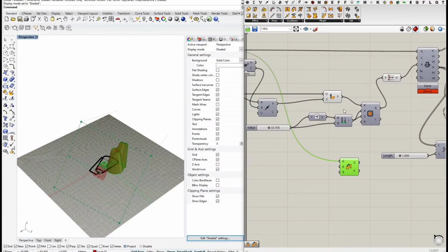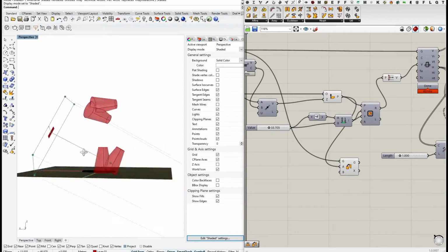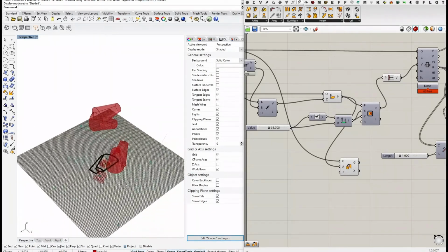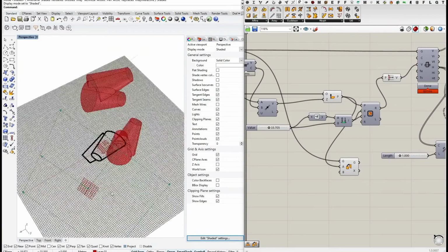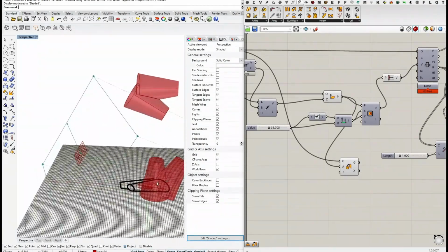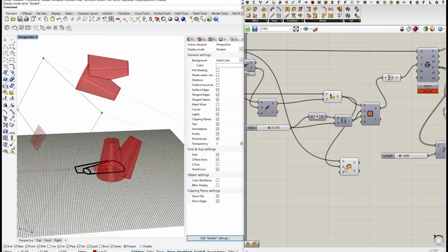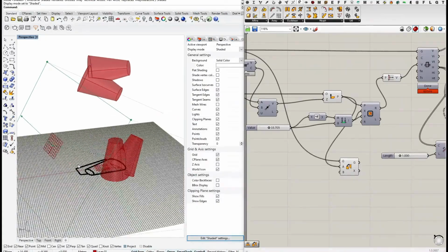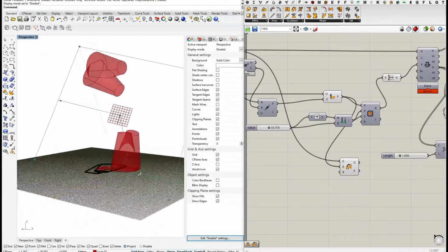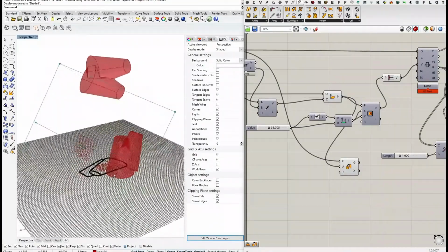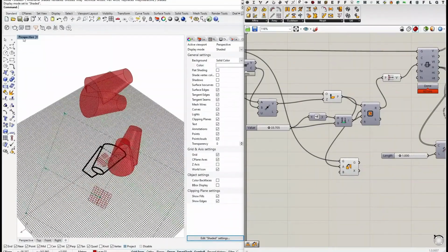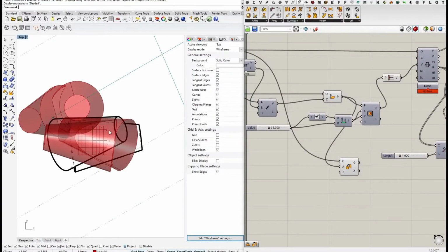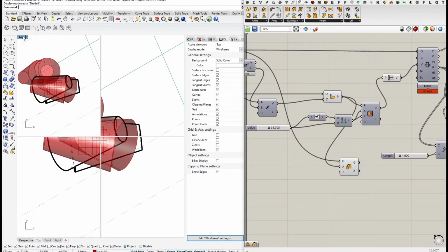So what we will see now is that if I plug this in directly, it would project it upwards, because the z-axis of our projection plane is pointing towards the object, and our end plane, our target plane, is, as for the Make2D drawing, the world XY space. So currently, with this vector, our space is actually inverted, and in top view it is mirrored.